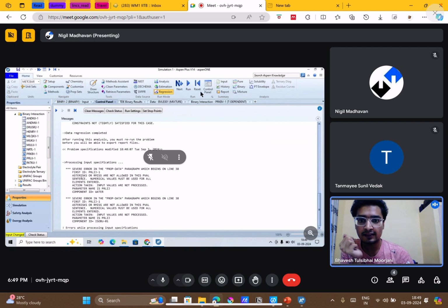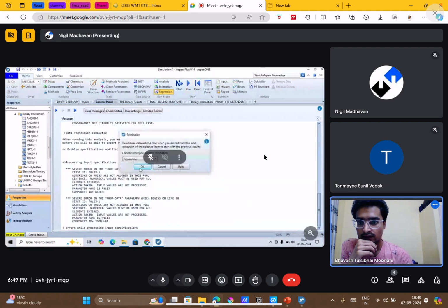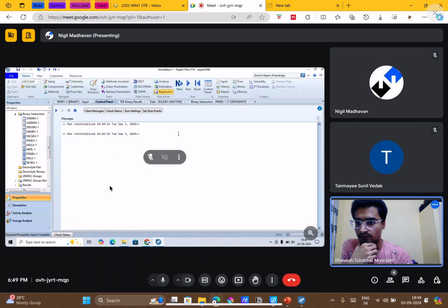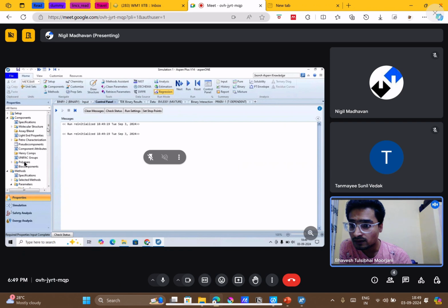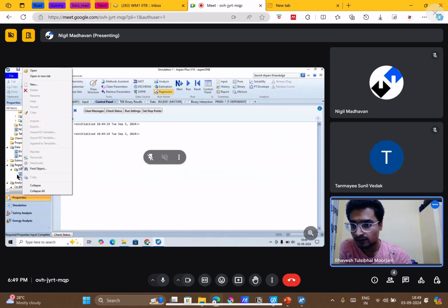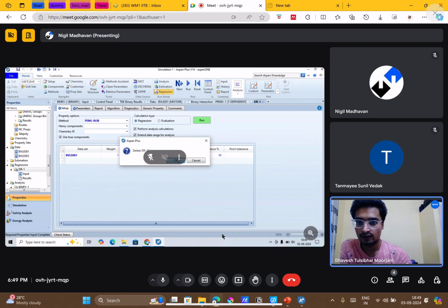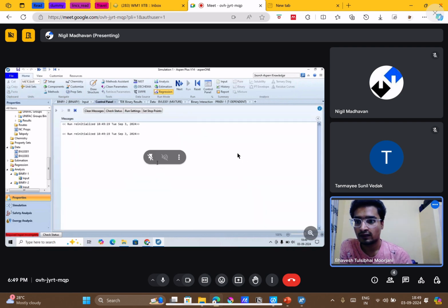Can you do reset simulation first? So on the top toolbar you see the reset option adjacent to the run. So reset it, purge all the parameters, do OK. Yeah, press OK. Then now on your left panel, remove that regression part. So go down, yeah, DR1, right click on the DR1 and delete it. Okay, yeah. Okay, now just do next and run the analysis one more time.